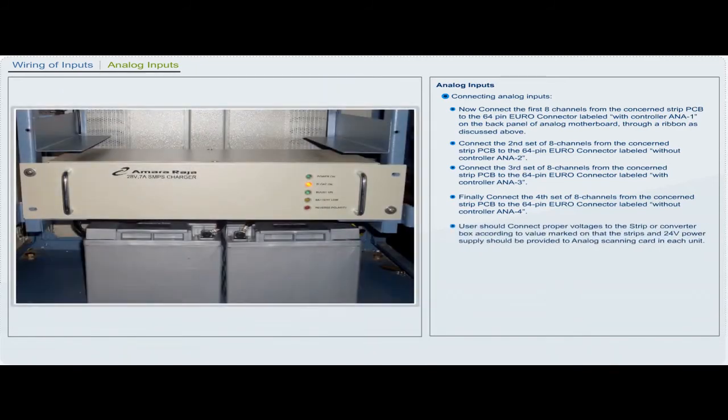User should connect proper voltages to the strip or converter box according to the value marked on the strips, and 24-volt power supply should be provided to the analog scanning card in each unit.